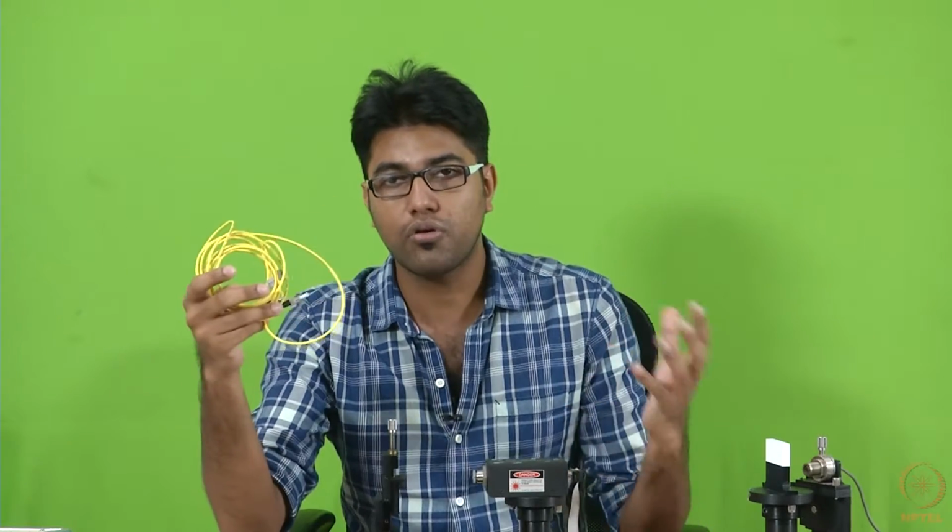So in the course, when you are learning the theory, you might have wondered, how are you going to put this laser light into this small optical fiber? As you know, the optical fiber is made of the core and the cladding. The core is around 9 to 10 micrometer, 9 micrometer in case of 1550 nanometer waveguides, so for a single mode waveguide. You might have wondered how you are going to put this laser light into the small 9 micrometer core. In this experiment, we are going to do exactly that. We'll couple light from the laser source into this waveguide, that is the optical fiber, and we will do that for different types of waveguides.